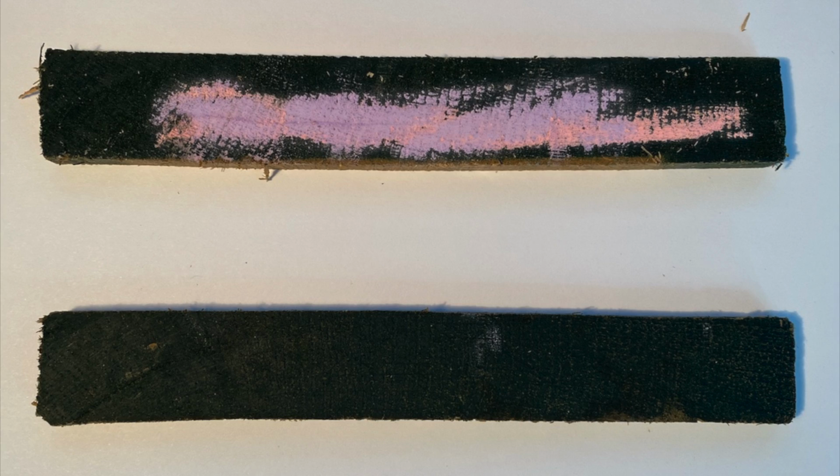At the lumber yard, I usually buy rough sawn lumber, which can be difficult to read the grain from by looking at it. And the ends are usually painted or sealed. So why would I buy rough sawn lumber when grain is so important? Well, the reason is that rough sawn lumber gives me more options in determining the final thickness of my parts and more material to work with during milling. It also gives me all the wood that I paid for. Plus, buying rough lumber can be a little cheaper in some cases.